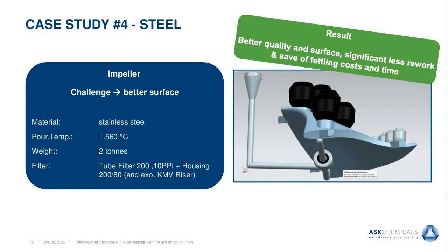I have only seen in some fettling shops, in some foundries, castings that really had holes in the wall. And all of these holes, and it was not only one, it was 2 or 3, had to be welded. How to calculate that, I cannot say. That is up to each foundry, what they calculate with their material. So from my side I cannot really say how much you save by using a tubular filter, or how much welding rod you save by using a tubular filter.